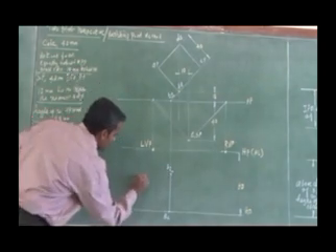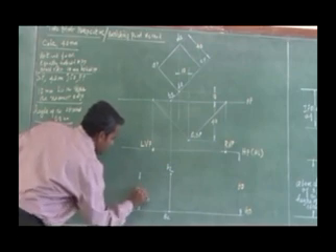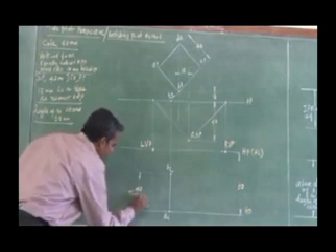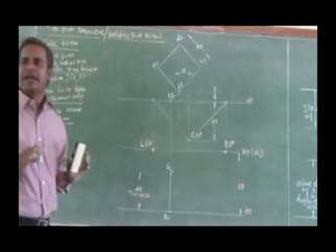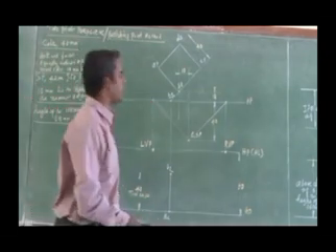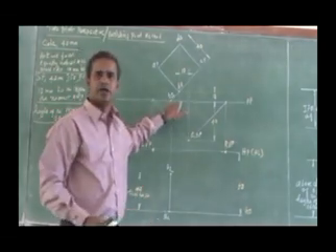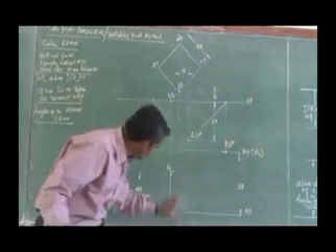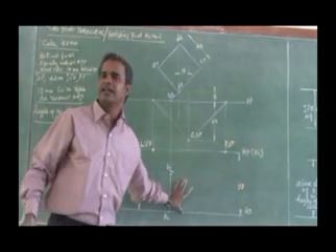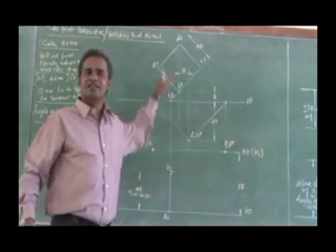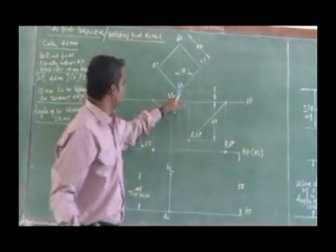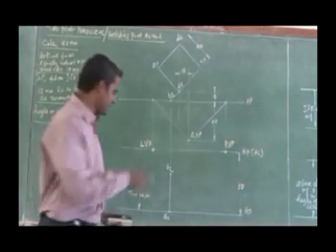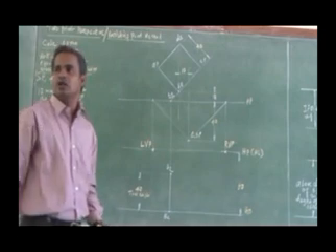So this is the 40 mm true height. This is the difference I have. Suppose the same corner is touching, I don't need to extend at all. If it is touching BQ, I just project that corner, mark that edge BQ, and directly get the perspective of BQ for 40 mm because that is touching. The true height I can get. Now since it is not touching, I am extending in one direction and getting the B2 Q2 perspective. But it is not the perspective edge of the actual cube.